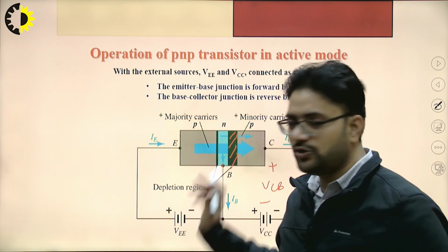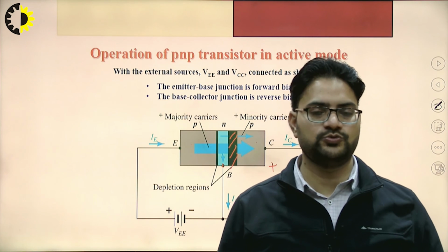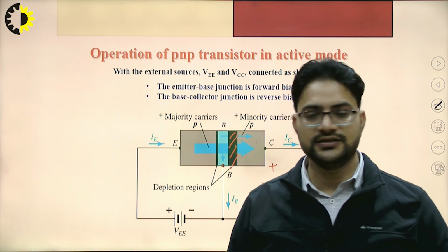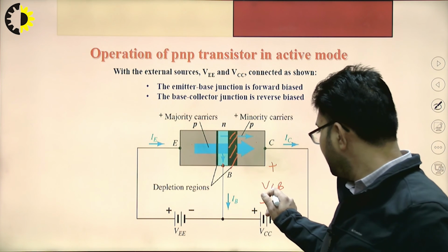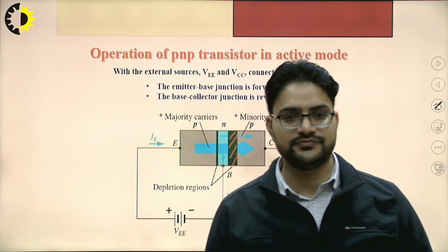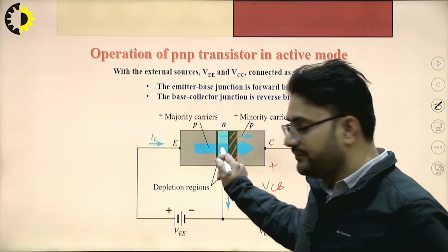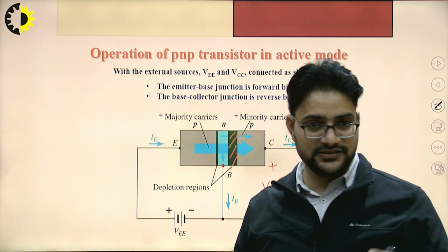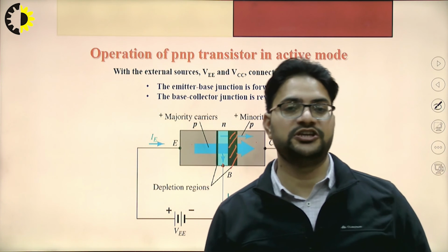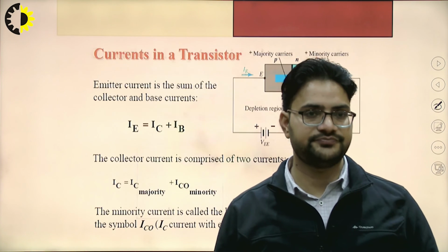This condition is called punch through or reach through. So a change in the voltage VCB is actually modulating the base width. This phenomenon is called base width modulation or the early effect.